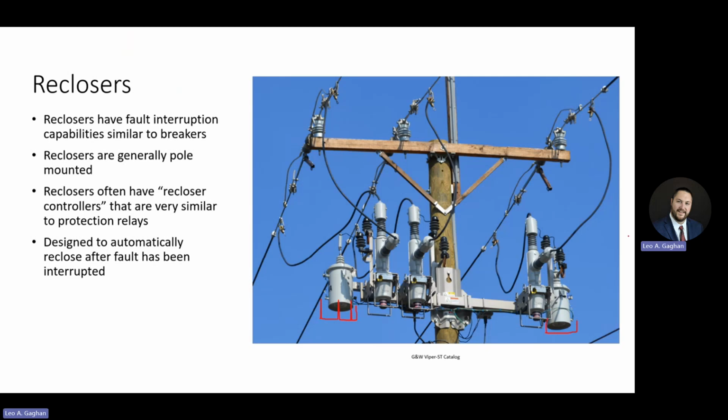They may be used to drop the voltage down in order to sense voltage on the line side or load side. Reclosers tend to use something called a low energy analog signal. Or they could be used to actually power the recloser controller. Right, drop it down to 120 and power the recloser controller.